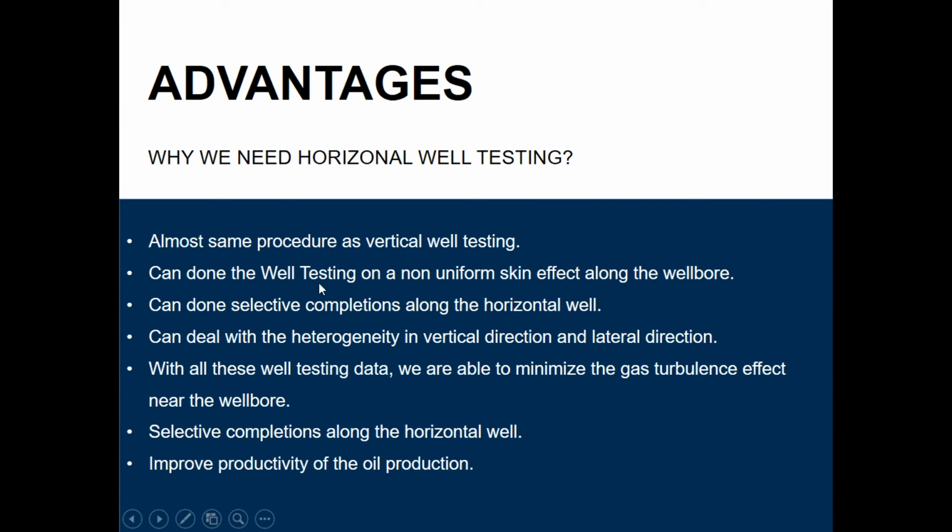Besides, horizontal well testing can be applied to study the non-uniform skin effect along the wellbore. The non-uniform distribution of the skin creates a challenging problem in the well. Hence, the well testing for a vertical well cannot be directly applied in a horizontal well. The interpretation of the skin effect and the well productivity also need to be modified.